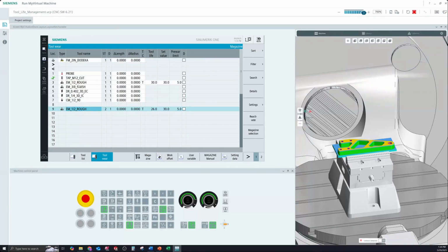So this is a 1/2 inch end mill. I build up a 1/2 inch end mill to be able to cut this part. I put it in a hydraulic holder, whatever I put it in. What I want to do is build a second tool the exact same way. It's got to be the same exact end mill, same corner radius, same length of cut, and all that. It doesn't have to be, because the machine doesn't know it's different, but it needs to be, right? So whatever tool I'm using for this, I want to build that same exact tool and enter it into the machine.